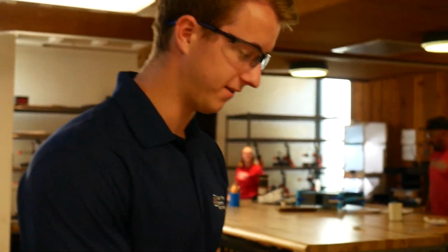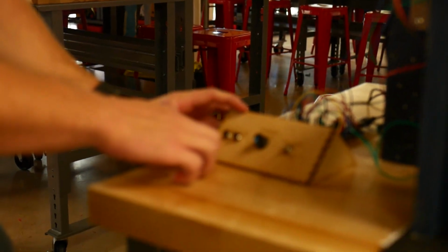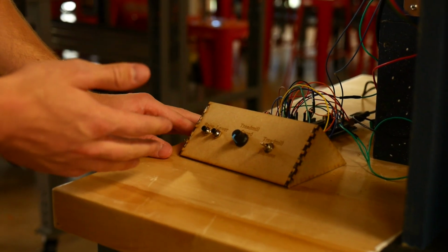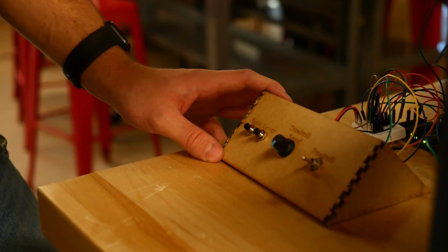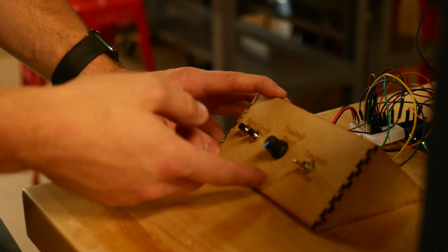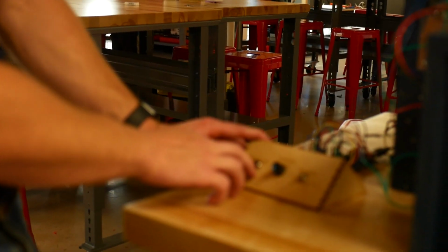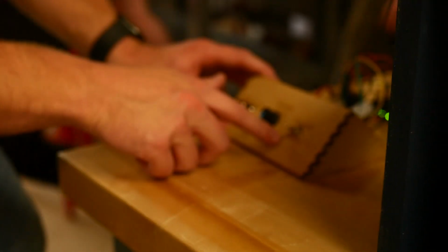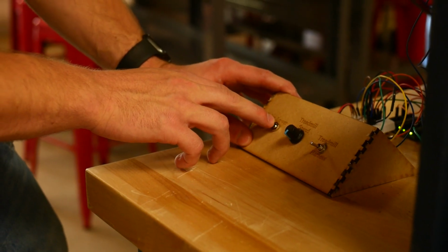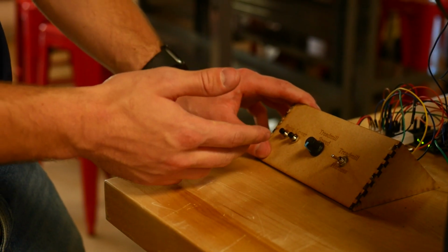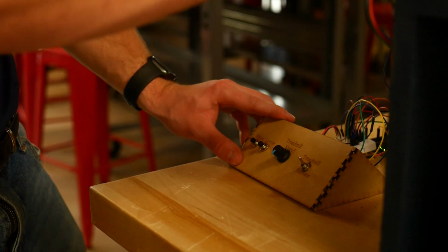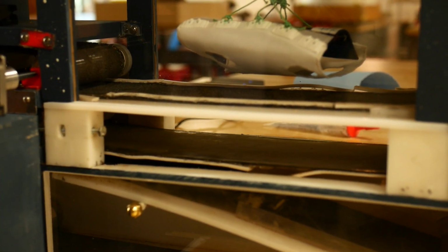And so for our user interface, we chose a minimalistic approach. It's only 4 buttons and pretty simple. It's run by an Arduino Uno with the program already installed onto it, and the Arduino Uno is just powered by a 5-volt supply. If you want to change the harness, you toggle to the harness mode, and you can raise or lower the harness depending on the force you need to apply. And we can switch to the treadmill, and this knob controls the treadmill speed for the stepper motor right here. All you need to do is turn it on, and it'll start running.